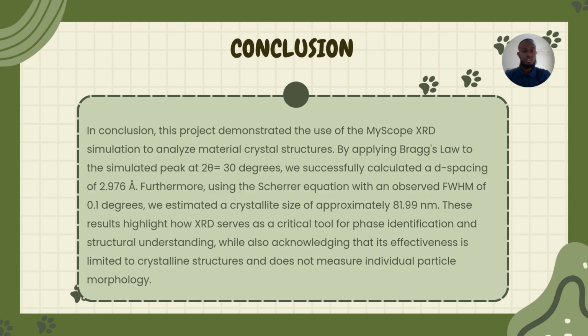So in conclusion, this project demonstrates the use of the MyScope XRD simulation to analyze material crystal structure by applying Bragg's law to the simulated peak at 2θ equal to 30 degrees. We successfully calculated a d-spacing of 2.976 angstrom. Furthermore, using the Scherrer equation with an observed full width at half maximum of 0.1 degree, we estimated a crystallite size of approximately